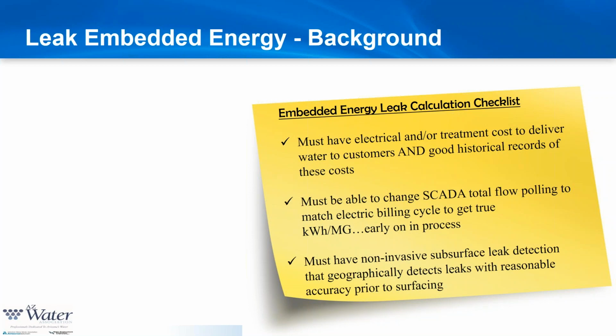And on top of it, you need to deploy a non-invasive subsurface leak detection that geographically detects the leaks with good accuracy prior to surfacing. That way you can pinpoint the leak when you find it, verify it, expose it, get a good gallons per minute reading, and then the next step we'll talk about is the flow duration. Does the system have to have a significant history of non-revenue water leaks? It helps, but not necessarily all the time, because as we mentioned before, if you have sandy soil, you could be having a significant amount of leakage and not know it.